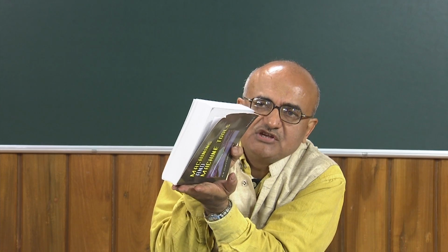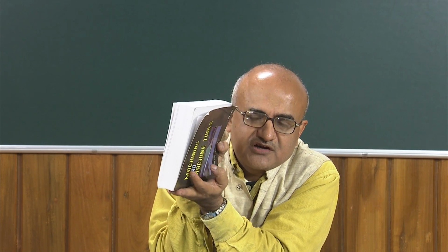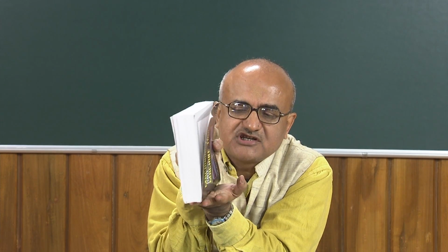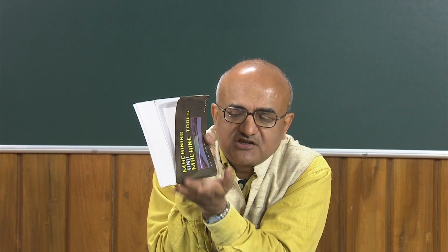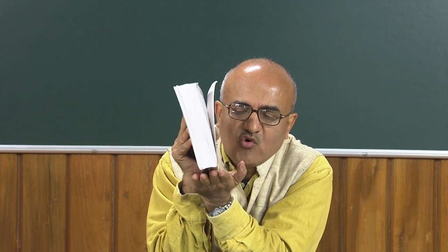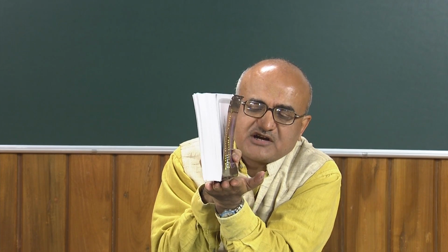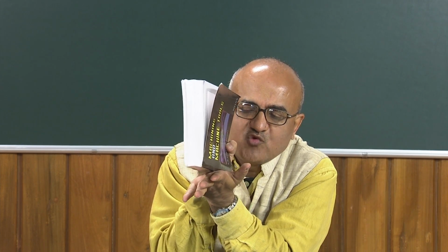If I incline it in the other direction, then in fact it will be compressing the chip, so it will have even more difficulty to move on the surface. So if I increase the rake angle, easy movement of the chip can take place, and this is this one. But now in this position, suppose I am moving this one on my palm, there is a lot of friction, so it is not moving properly.